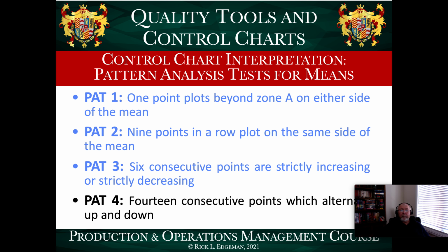You use a separate control chart on each. Machine A gets its own chart. Machine B gets its own chart. The first shift gets its own chart. The graveyard shift gets its own chart. Okay, so those are the 4 patterns. These 4 patterns apply literally to any type of control chart that you might encounter.